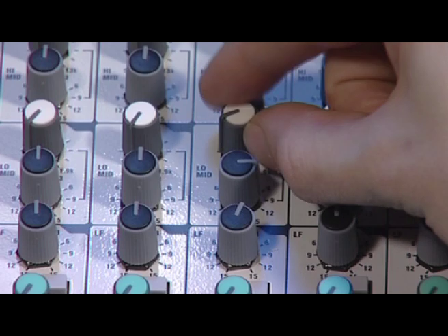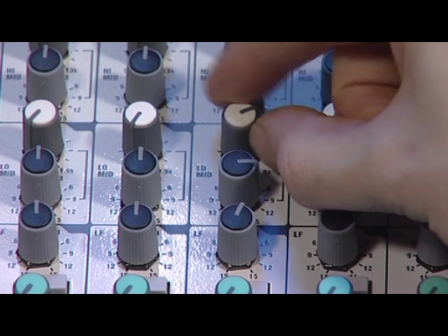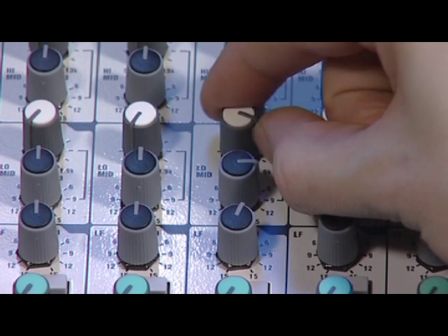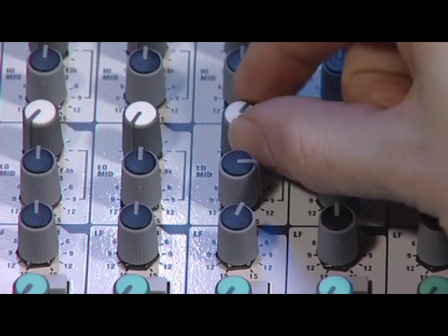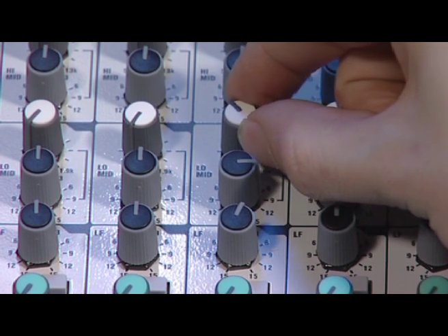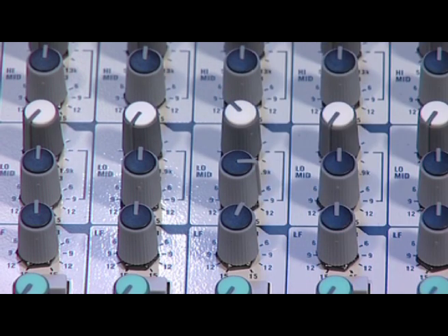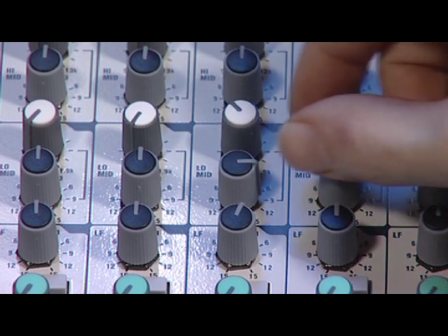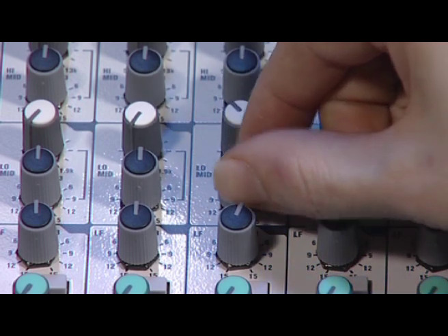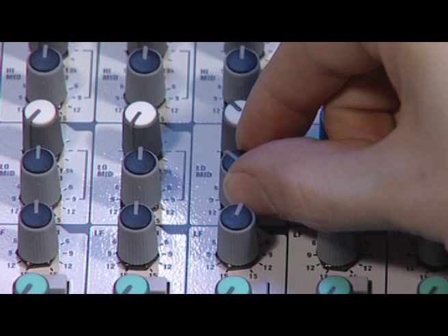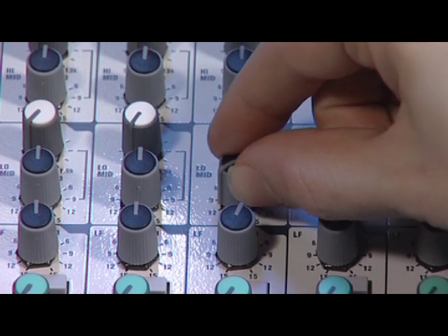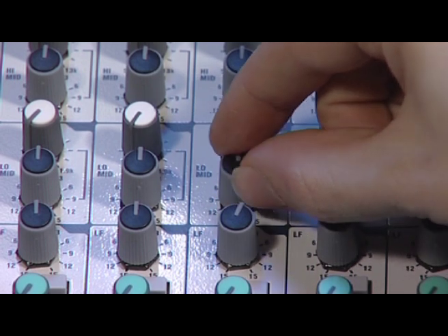Turn the gain up on the mid-frequency section. Sweep the frequency around until you locate the aspect of the sound you want to modify. Find the exact spot where it sounds most annoying. Now rotate the knob from boost to cut. Choose the amount of cut that sounds best. Even a small amount of cut can have a hugely beneficial effect.